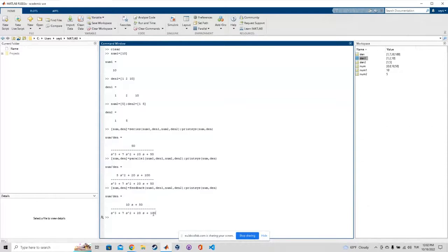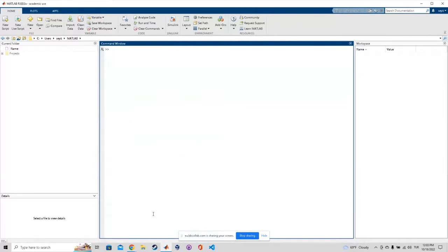Okay, let's say now we try to find zeros and poles of a transfer function, right? Here on our screen, our numerator equals, let's say, 0, 8, 9, 7. Doesn't matter. Let's say our denominator equals something else. All right, we define our numerator and denominator, and we want to find zeros and poles of our function. How do we do it? Let's define these two, and then first you write z for the zeros, and then you write p for poles, and then k for your gain, all right?